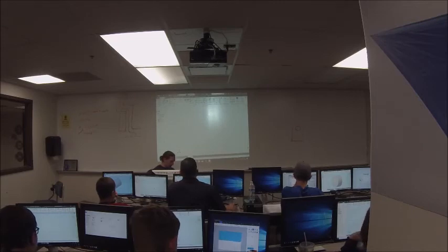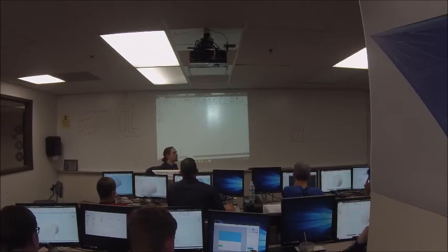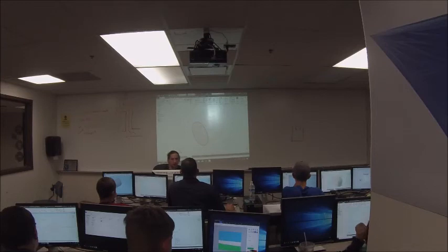Okay, everybody have a cylinder? Okay, so sometimes you want to cut. Sometimes you want to take material away from a part rather than adding to it. So let's create a sketch on the end of this cylinder. You guys remember how to do that, right? Click sketch, click the face that you want the sketch to go on.